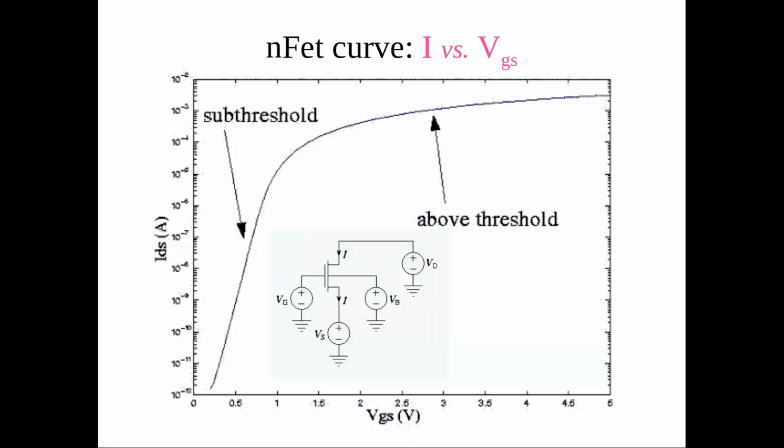Why is it VGS and not only dependent on the gate voltage? That goes back to these movies that Toby was making. You really need to do it relative to the source and the drain and the gate. The barrier has to be small. So it's either the barrier between the source and the gate or the barrier between the drain and the gate, but the barrier between one of the two terminals has to be smaller. So that's why it's VGS. It's always a difference.